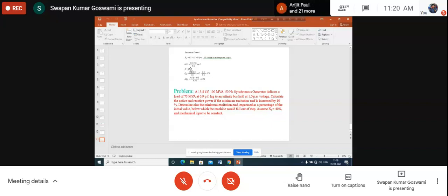That is again a slight variation. Previously it was 9.6 degree. Now it is 8 degree. So variation in field current causes a small variation in delta. We cannot say that it is completely decoupled. There is coupling, but again the coupling is weak. From 9.6 degree, it becomes 8 degree when the excitation is increased.